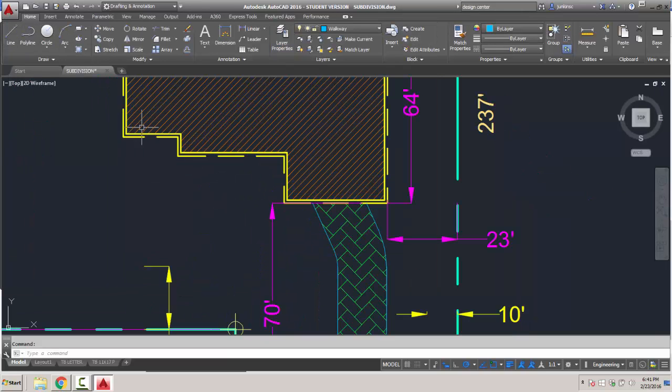I'm going to come back up here. I'm just going to take my polyline, and the dimensions are from the outside of the house itself, 14 foot 6 over. Of course, they show a little porch on there. So we're just going to kind of draw this from this area. We're going over a distance of 14 foot 6 inches.